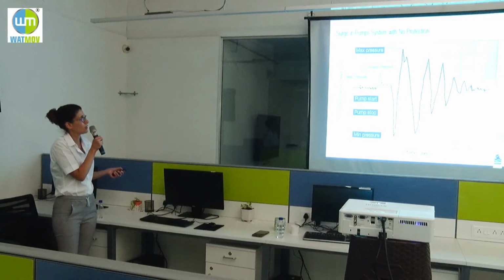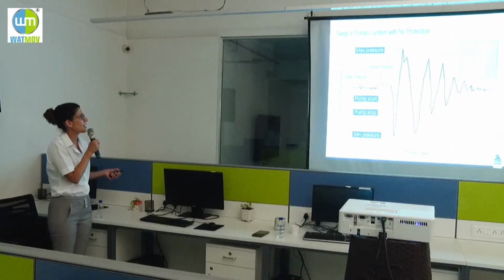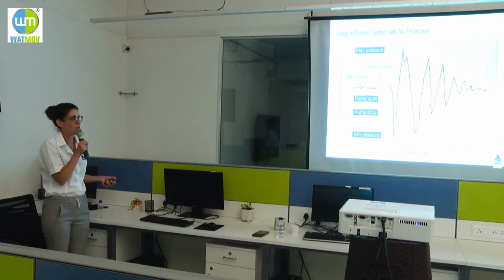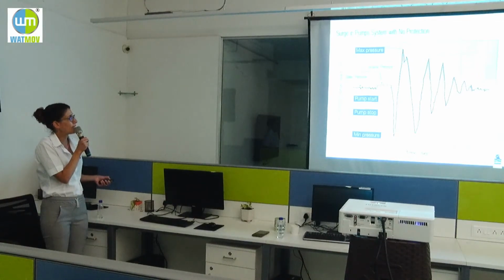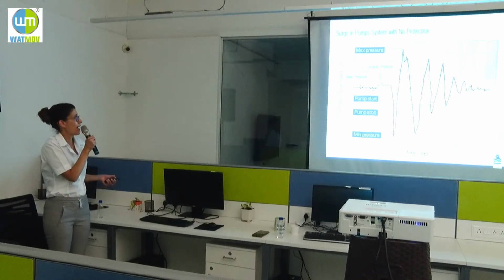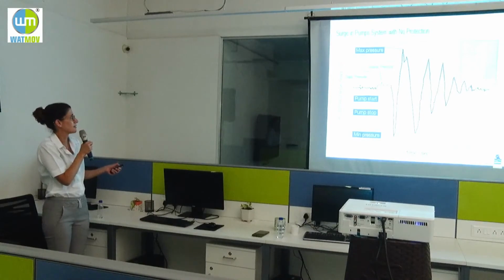And now there is a pump stoppage, a power failure, and the pressure is dropping dramatically. It's still above 1 atmosphere, but it's dropping dramatically. So the pipes experience low pressure, and then it's increasing. So this is the negative wave that we talk about. All this envelope is the negative wave, when the column of water is pushed up. And this is the positive wave.